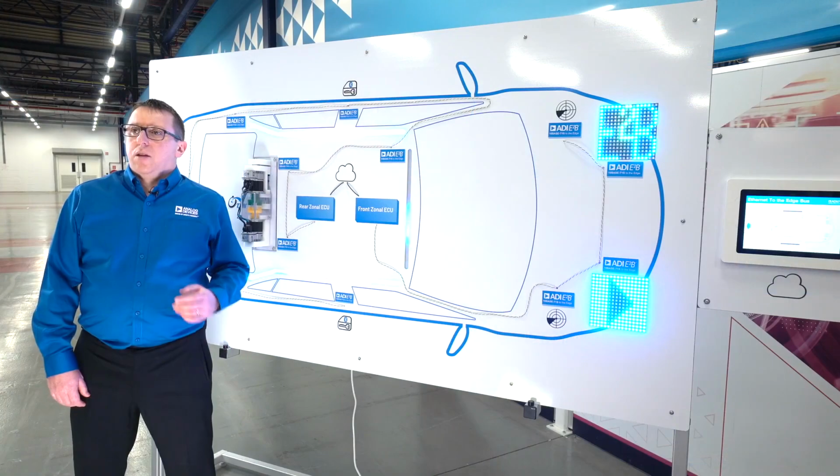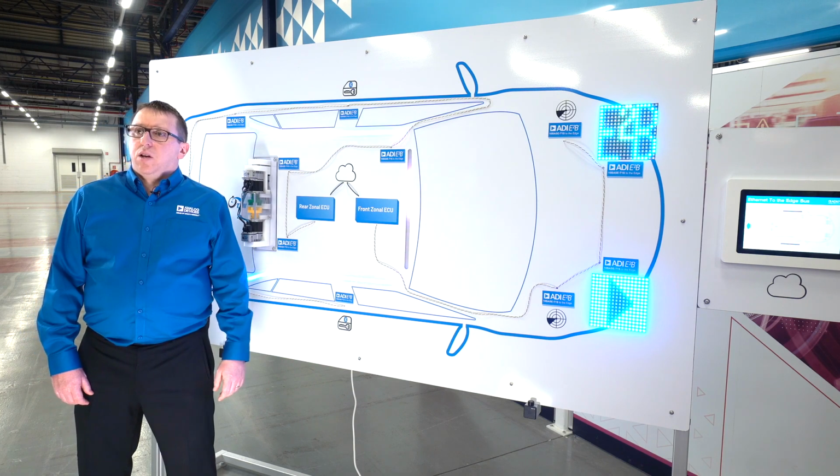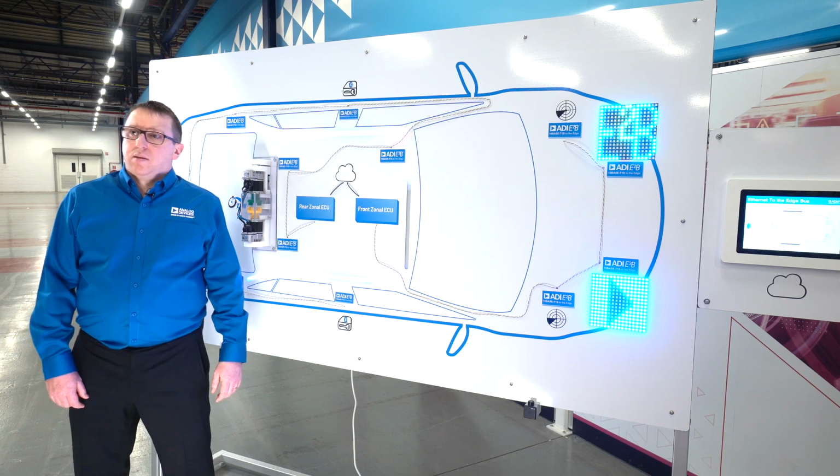Note that all of these edge nodes use E2B in low complexity Ethernet mode, meaning that there is no MCU used in the edge node for the Ethernet communication. The demo illustrates some of the wide variety of use cases that can be addressed by E2B 10BASE-T1S.